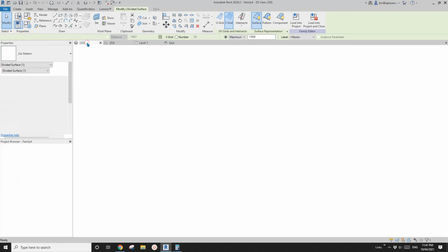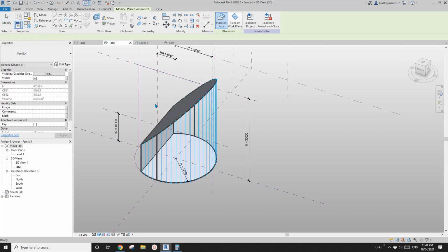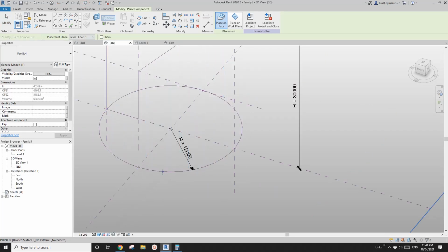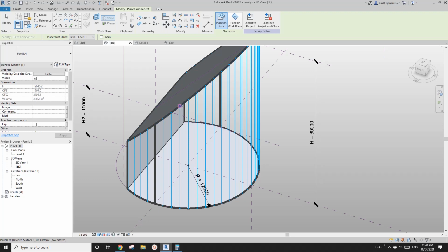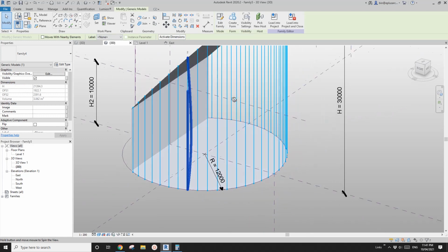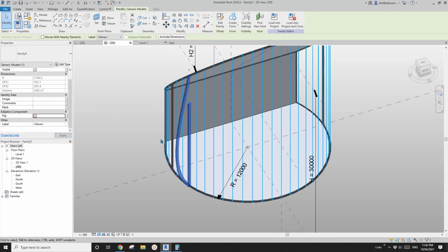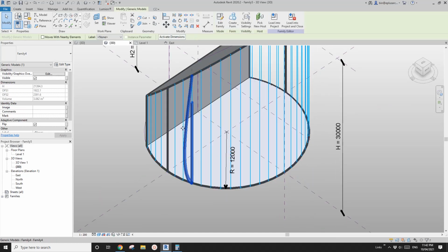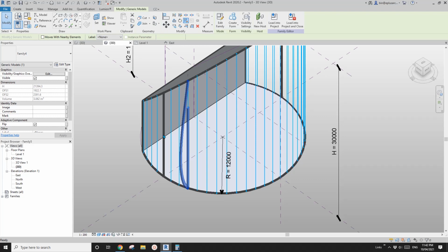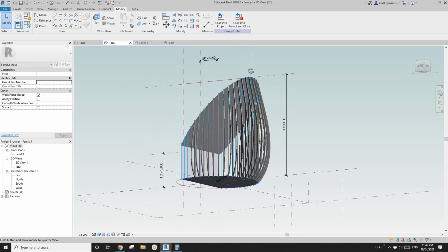Now let's go to the frame, load this into the mass. Let's go to 3D view. Let's place it. So 1 and go up here. It looks like it's in the other direction. That's fine. Select this one, select the frame, and check this flip. Now if you select this adaptive family and click on repeat and wait for a few seconds, you will see we have this.